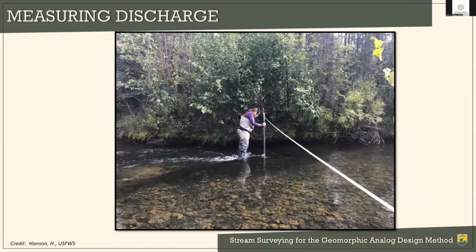Also, as Franklin mentioned yesterday, you can measure discharge when you're out there, and that can help you to understand low flow conditions, or it might help you to calibrate a HEC-RAS model if you're using one.